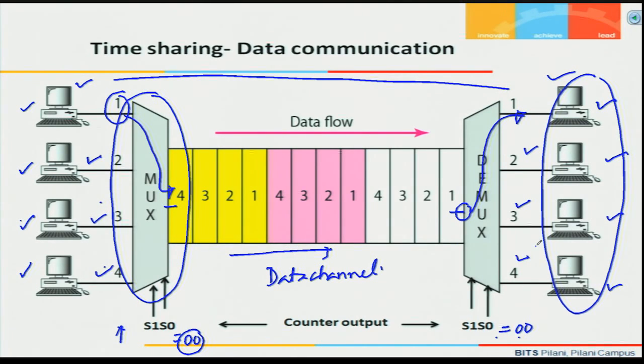But you will find here that at any given point of time only one transmitter can transmit data through a common communication channel to a receiver. The way it is transferred depends on the values applied at the selection lines. So I could use a counter whose values could change, for example, from 0, 0 to 0, 1 to 1, 0 to 1, 1.